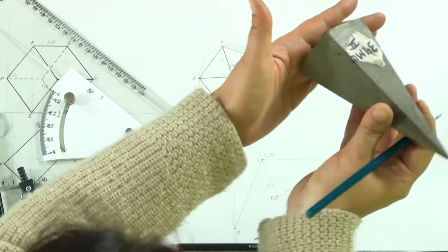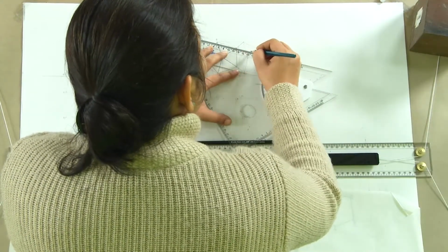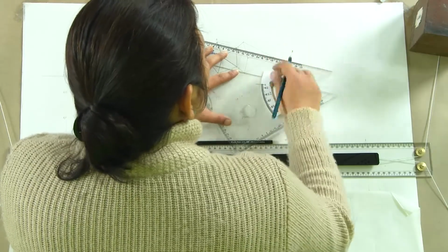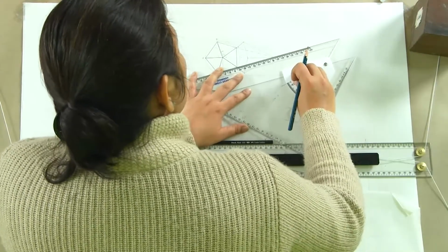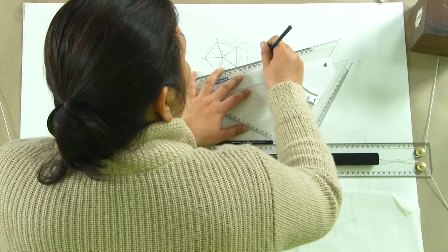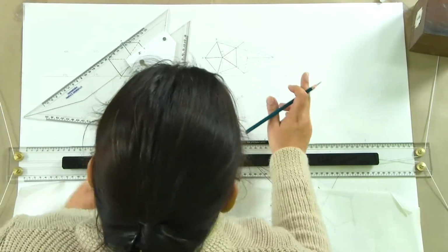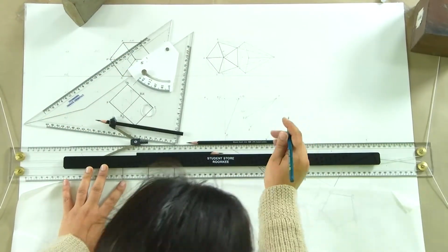So if this was rotated like this, what we see from the front is these two faces, while two faces go at the back, and one of the faces, if I draw the hidden line here, this face, which is a triangular face named OCD, is going to be the face which will actually be seen in its true dimensions, because it is absolutely parallel to the VP.